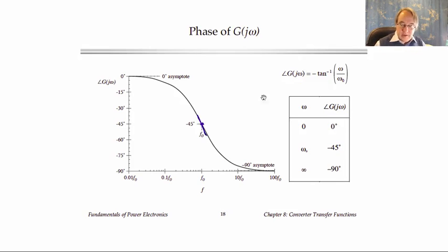It's actually a little tricky because you have to vary frequency in this logarithmic form and then take the derivative of that. But we can do it, and if you do that, it turns out that if we draw a function with that slope and extend it up to the high and low frequency asymptotes, then this break frequency where the asymptotes intersect turns out to be equal to e to the pi over 2 times f naught.